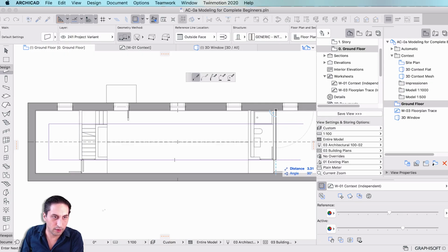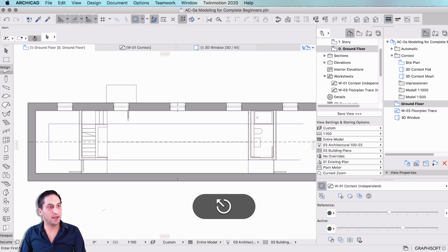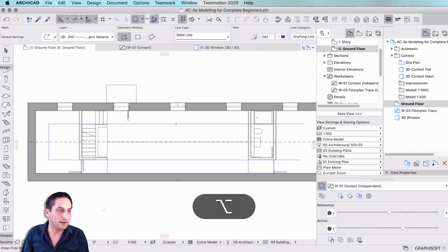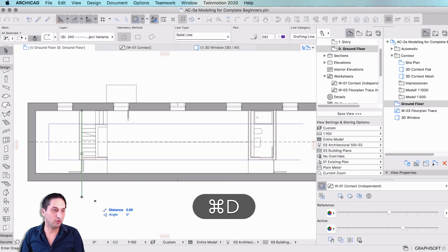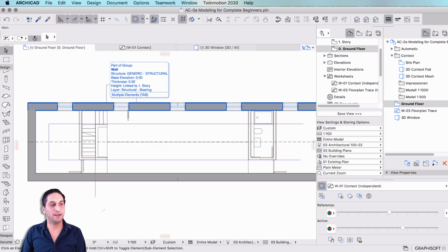Here, one click all the way to the line, then all the way back and going back up. Again, we try here, we change its side. Here we go all the way back, and then we're going to have the same problem again. So escape to change command, Alt to pick up the polyline that I did before, then click once and double click here to draw one of those lines. We click to select, Command D to drag, and then we drag it to 0.9 centimeters from the original wall. Now we also again have a line that we can work with.